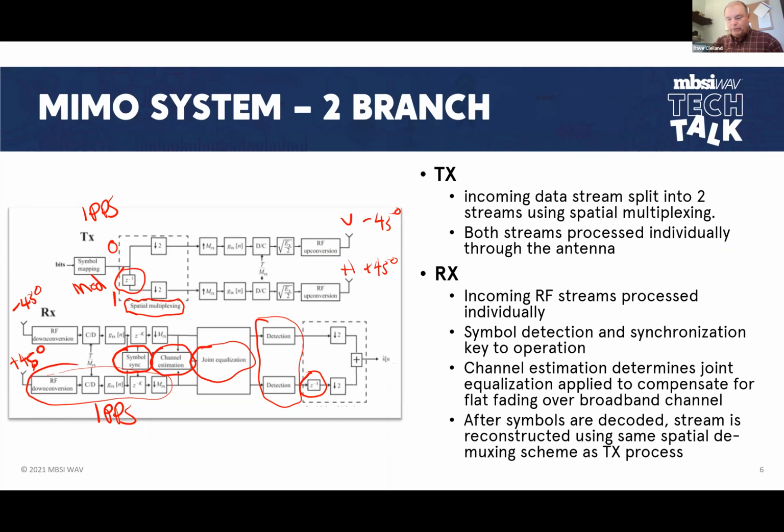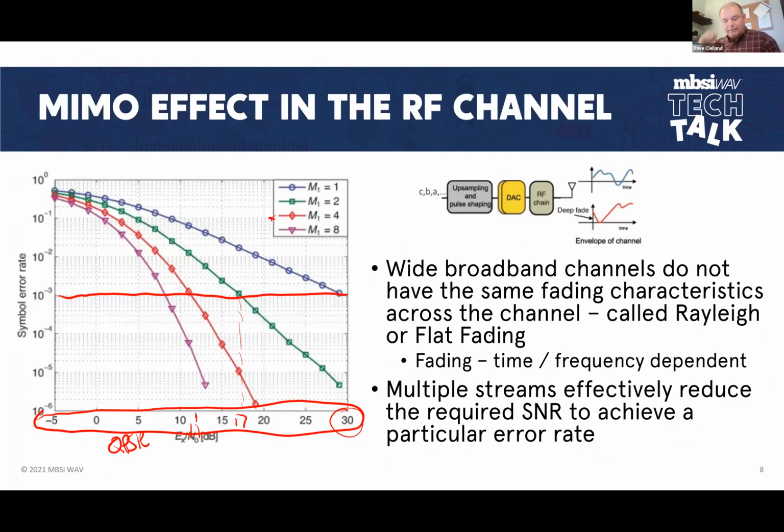So it's real important that when we're running a MIMO system, we have proper connections to all of our antennas, both at the CPE and at the base station itself, or in the case of the point-to-point world, at both parabolic antennas on either end, whatever it happens to be. We need to make sure that our connections are good, so that the equalizer and that channel estimation algorithm, the CQI, works properly. All right.